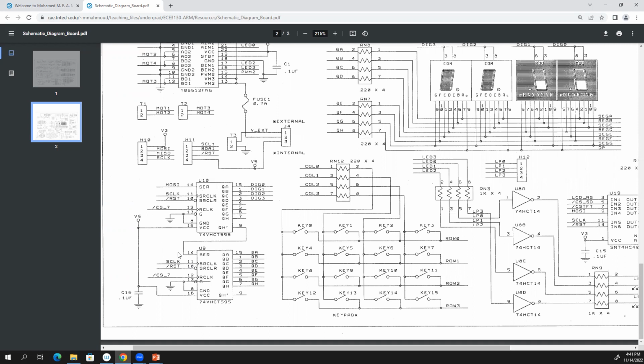So they are going to be connected as one big shifter, just 16 bit. That's why I have to connect this shift clock with the shift clock. At any time when I shift, this one is going to shift, and this one is going to shift. Also, when you do the latch, as I explained to you before, this one is connected to this. It's too much detail, so let me give you the conclusion.